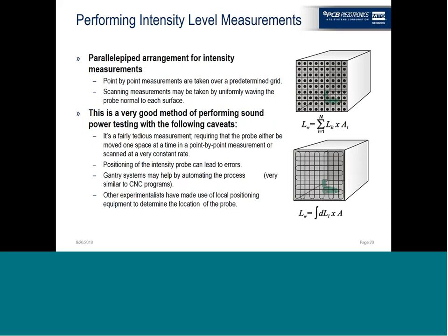The important thing to note whenever you're doing any type of sound intensity measurement is that your background noise needs to be constant. That's not to say that you should turn on a noise source and have it always be on. But what I'm saying is if someone's doing work in a room next to where you're doing the sound intensity measurement and you finish half of your measurements, go to lunch, and you come back and that person's not there doing the same type of noisy work, your measurements will be completely off. You will actually have tainted them because half of your sound intensity is measured one way and half is measured another way.